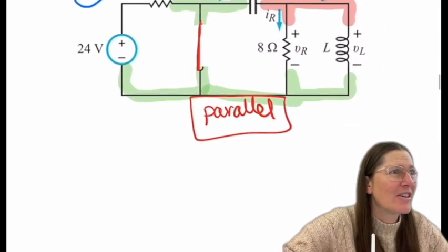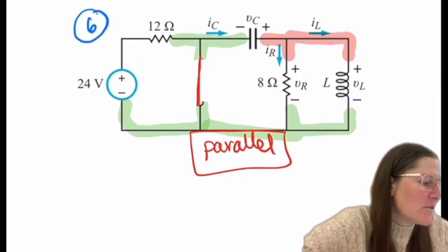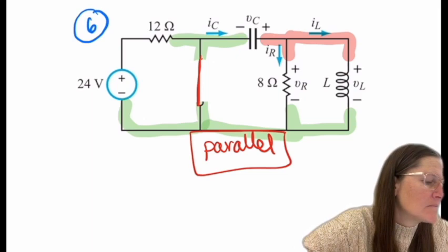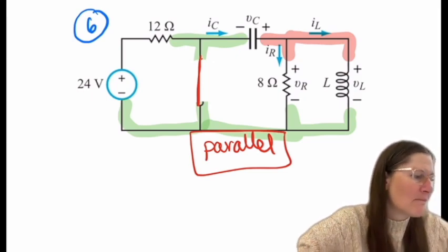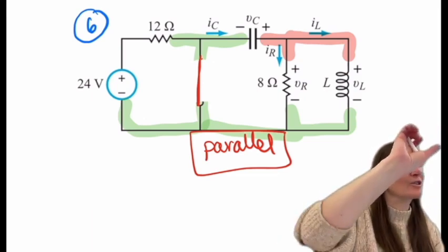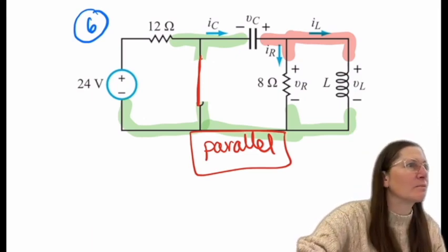Yes, Kyle. So, in the initial stage, with that switch open, and the voltage source shooting current into the negative terminal of the capacitor, are we assuming that it's non-polar, and then we can just have a negative voltage on the capacitor? Yeah, so you would end up with a negative voltage, most likely. So when you drew it, you could either swap the polarity and make it positive, or leave the polarity plus minus and put minus whatever value.